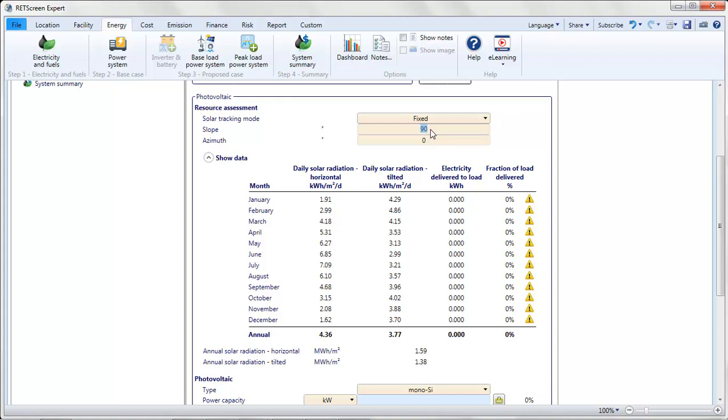If we put it on the roof, maybe the roof is at, say, a 20-25 degree slope. Maybe we can tilt these up a little bit. So let's say we get this to a 30 degree slope. That should allow some snow to run off it as well. So I put this at 30 degrees and I see that overall the impact is not so strong in winter now, but I still get lots of solar collection during summer.